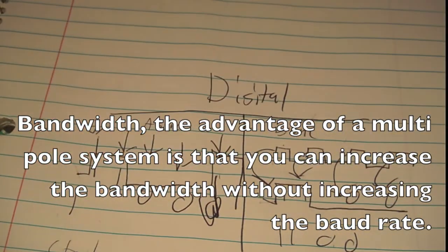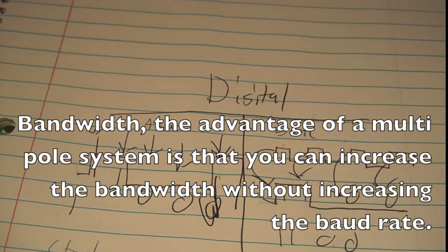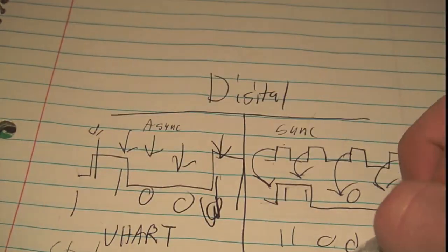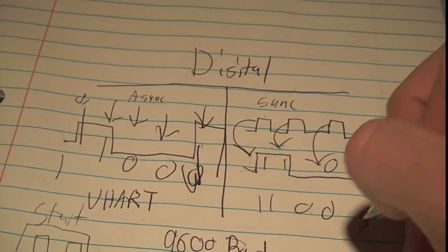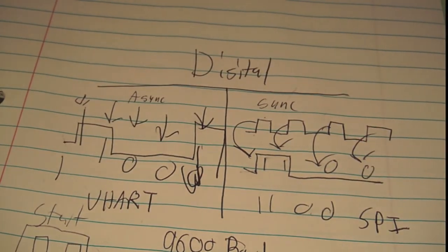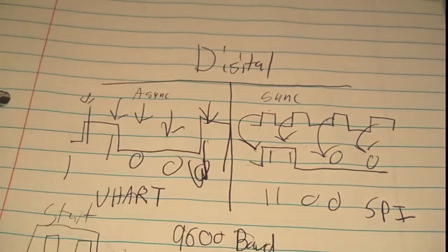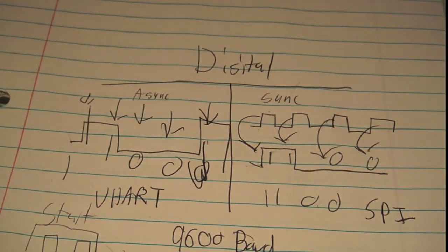And so things that are synchronous versus asynchronous, right? You have UART, which is asynchronous, whereas SPI is synchronous, because SPI has a clock signal. Okay, so I2C has a clock as well. That means it's going to check on the rising edge of the clock. The data rate isn't specified. It's specified by the clock rate in that specific instance.